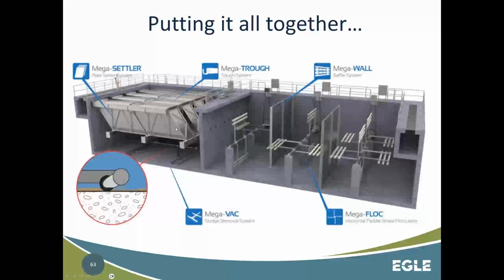And then of course over here, you can see that basically what's happening is the water's coming through, it's hitting these plates. And as we saw in the demonstration, the particles only have to fall the distance until they hit the plate. And then once they do, they're going to slough off to the bottom. Whereas in a traditional basin, they'd have to settle this whole length. So a particle starting here only has to fall until it hits that, boom, it's down, rather than settling all the way down the entire column vertically. And once it hits these plates, the water that rises up ends up in these collection troughs down here into this large collection trough, and then that's headed to the filters.